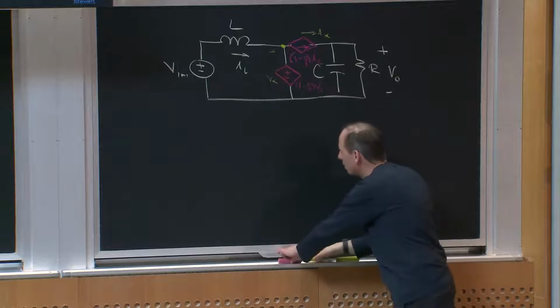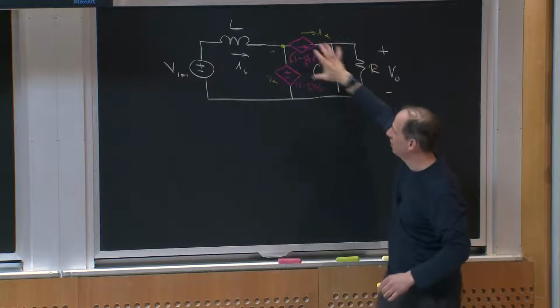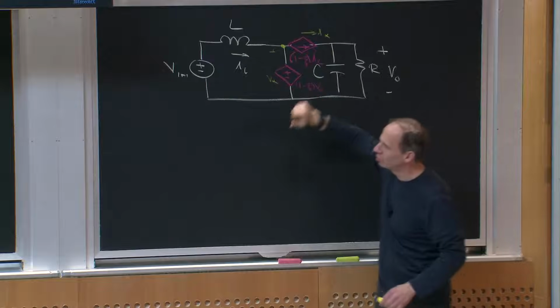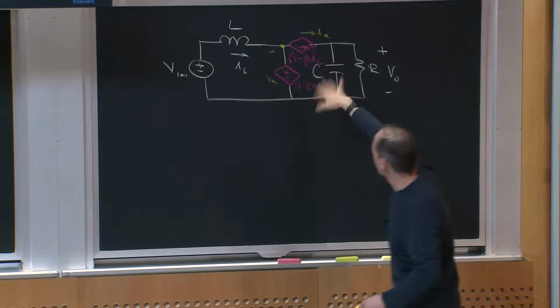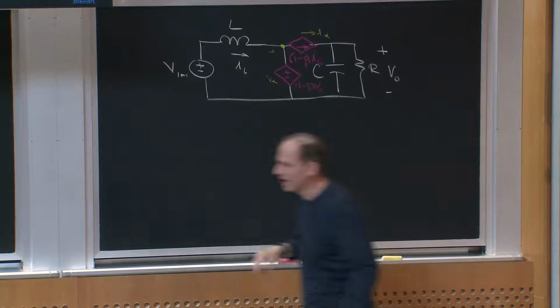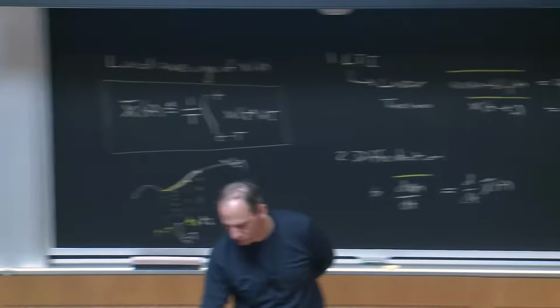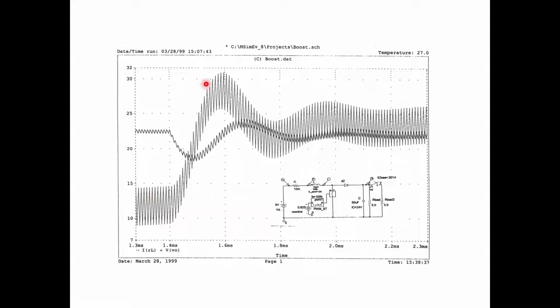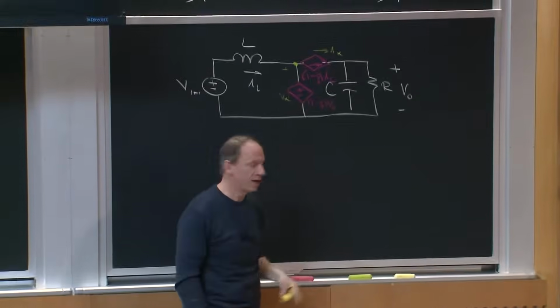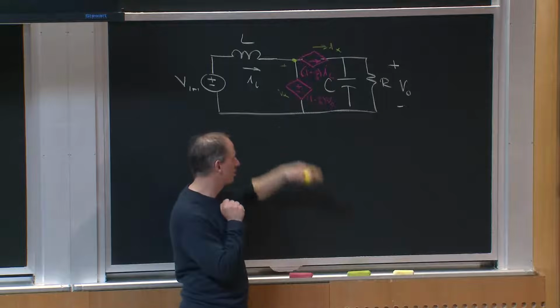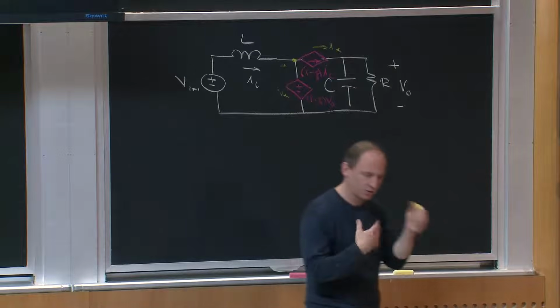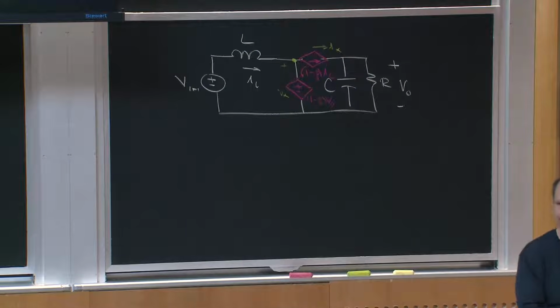So, this is still a switching circuit, right? In fact, if I simulated this circuit and I ran a controller and had some Q of T, I could simulate this and it would generate exactly this switching waveform. If I told you Q of T is the constant duty ratio here, and I simulated this circuit with that Q of T, and I changed the load resistance, I would get exactly that response. Okay, so as long as I'm in continuous conduction mode, this model represents that circuit.